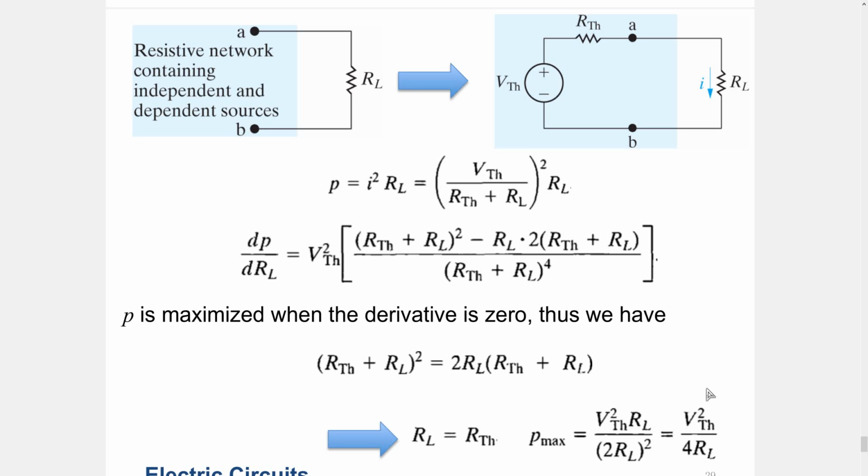reactance with your load. This is especially important for factories where there are lots of reactive components like inductive machines, etc. Not that important for the home, especially in energy delivery, or for RF circuits. This is very important because you want to match the impedances for maximum power transfer. Otherwise, you will be losing unnecessarily, you will be wasting energy, and you don't want to do that. So a topic called impedance matching, a field of research for RF engineering, for instance, deals with this